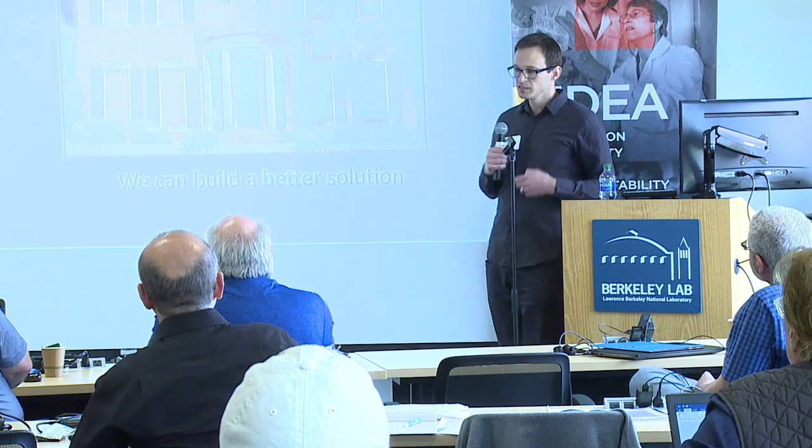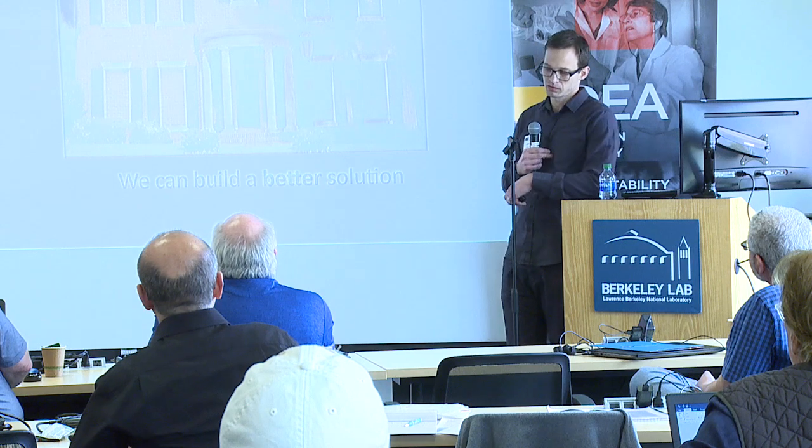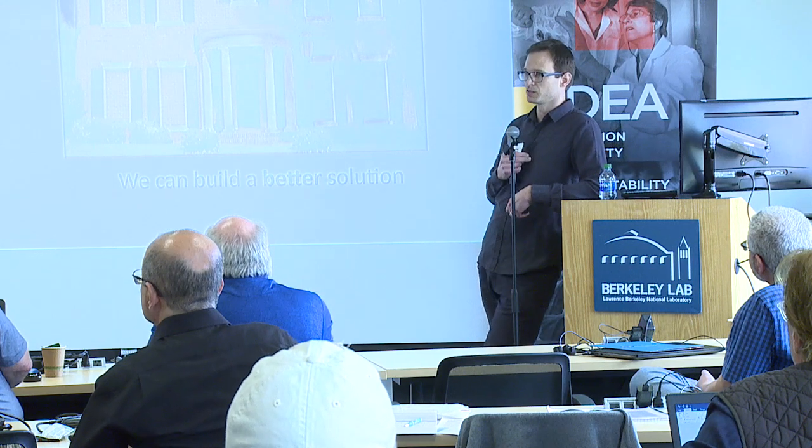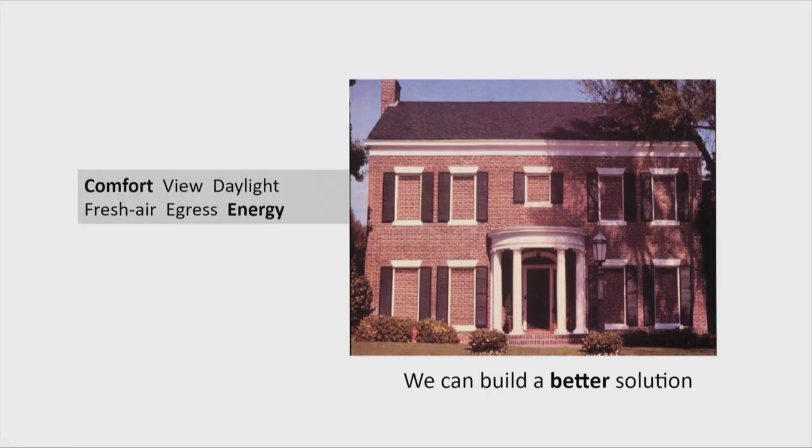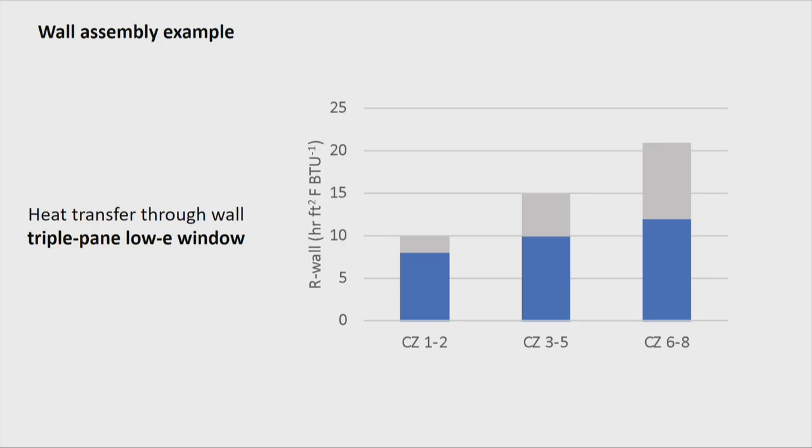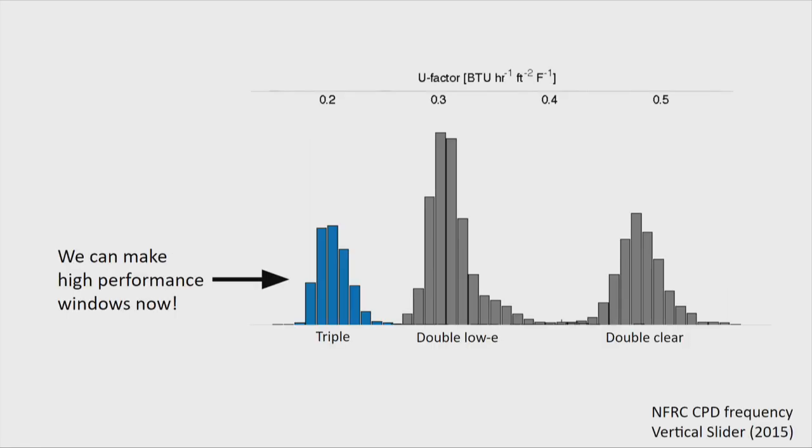So the easiest or most incremental approach or solution, it's not even a solution, but it's the next step along the way to help solve this problem, is triple pane windows. In our climate zone, that R7 wall becomes up to an R10. That's a pretty good improvement for a technology that's been around for a very long time, right? So if we think about trying to get the whole US to the next level, we're trying to think of these incremental steps.